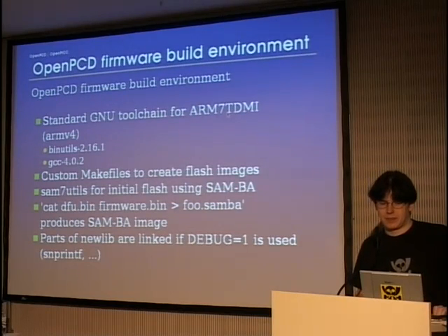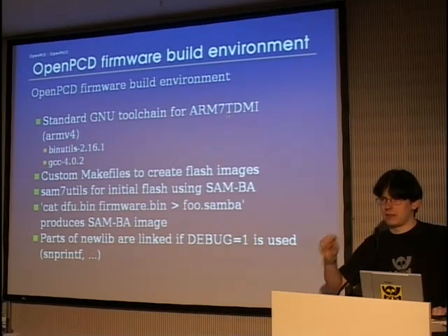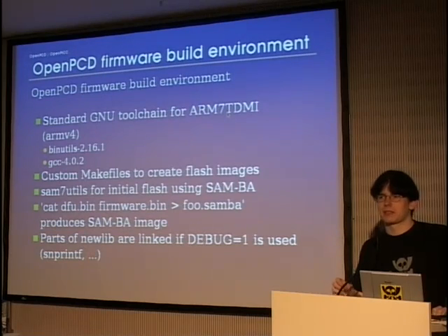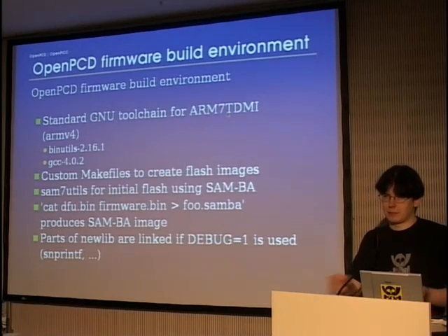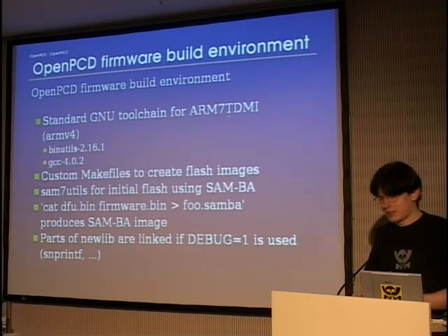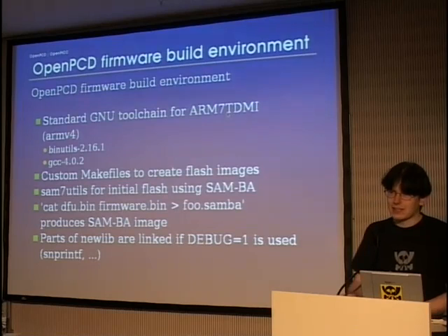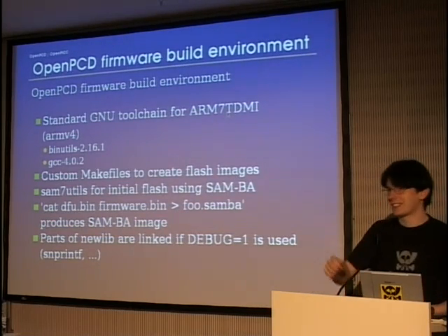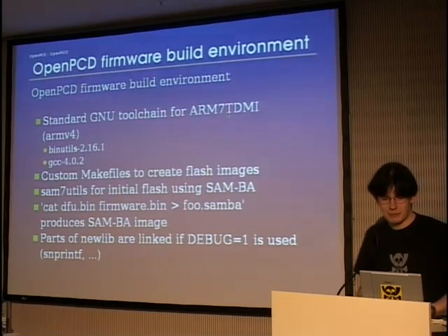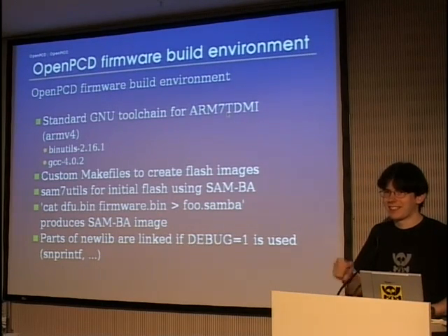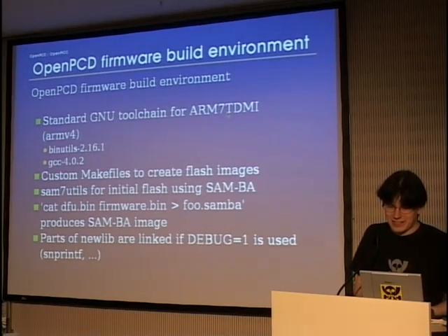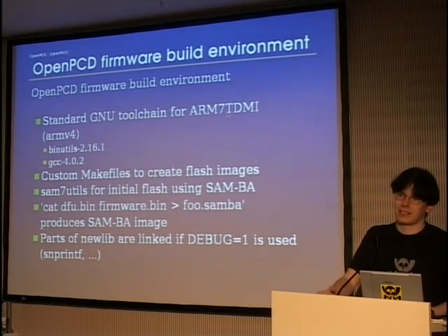This is a built-in mechanism in the Atmel microcontroller that we use. It's a little bit clumsy. You have to first disconnect it, then set a jumper, then reconnect it, then wait for 10 seconds, then disconnect it again, remove the jumper, then connect the device again, and then you can flash over USB. If you don't wait 10 seconds long enough, it doesn't work. So this is the last resort, which we can always use. We use that for initial programming of the device, and you can use it if you brick it otherwise.